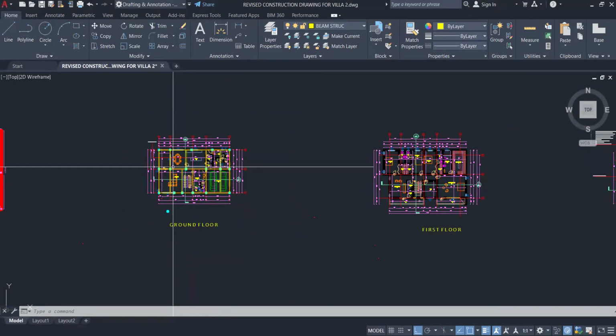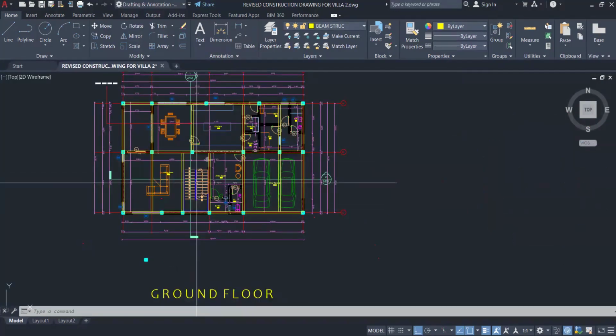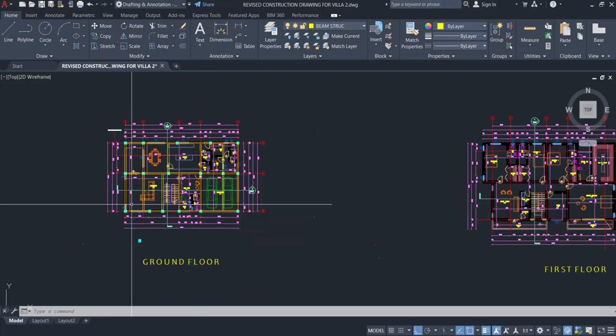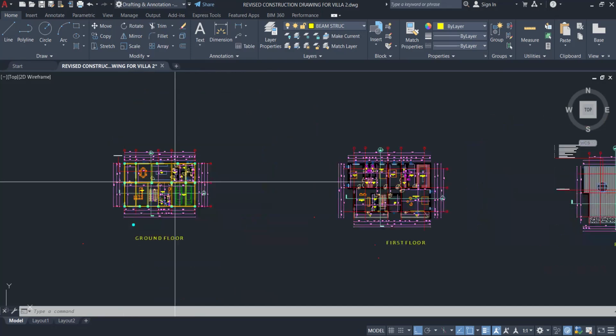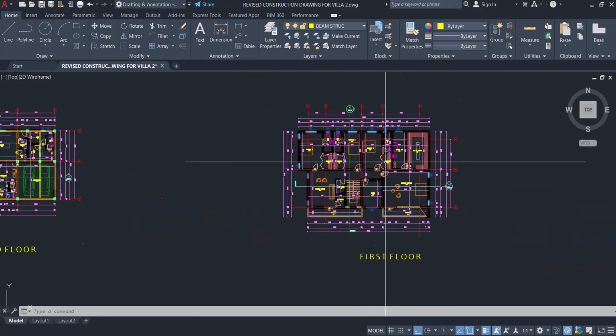So now that we understand that, the next thing we want to do is support the first floor. The ground floor is on the ground. This ground floor that we are placing our column and we are putting the beam on the wall is on the ground. That is not what we want to support. What we want to support is the first floor. That's why we call it first floor GA or first floor layout. If you say second floor layout, what we are saying is we want to support the second slab. I hope we get it. So now all these columns, they are coming from the ground. This is what they actually want to support, this first floor. Are we getting it?